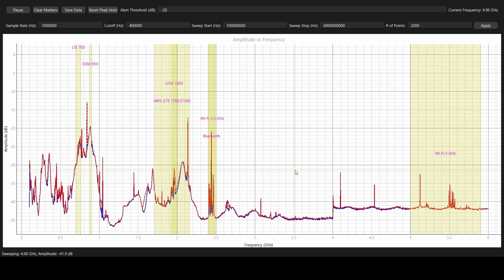In fact, in another video using our frequency analyzer that we made with ADALM Pluto, I'm going to show the transfer function of the antenna, because the antenna has some null frequencies in it. But for this purpose, I just thought to go with this antenna. You can see the spectrum. The sweep starts from 100 megahertz all the way to 6 gigahertz, and the number of points for this case is 2000.